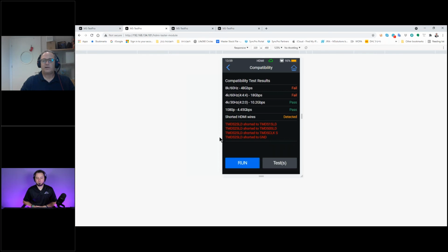So those lines are actually shorted. In certain situations, it will be fine. But we need to understand GND, for example, the one that we are seeing here, is actually the reference line for the DDC line. DDC line is the EDID that you are reading, or the HDCP, which is going. Any interference that might go throughout the video might affect, this way or another, the GND level.